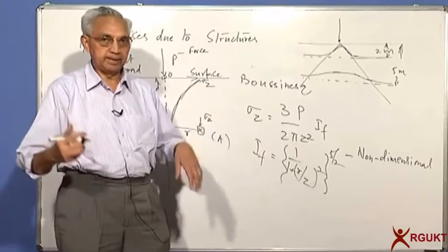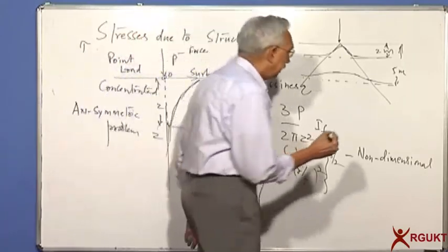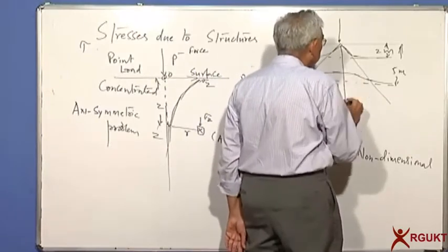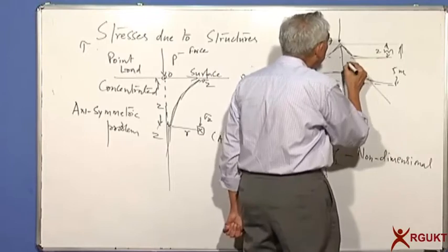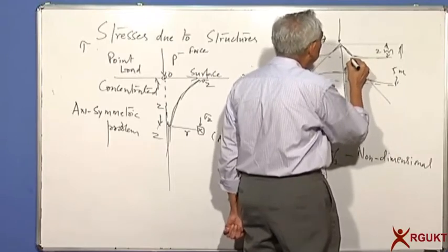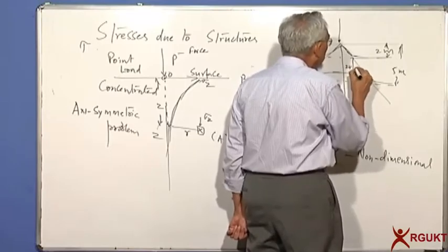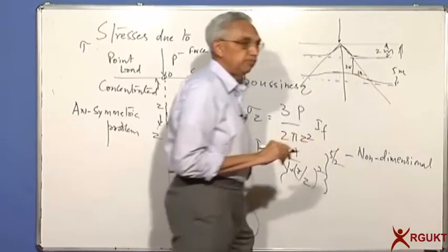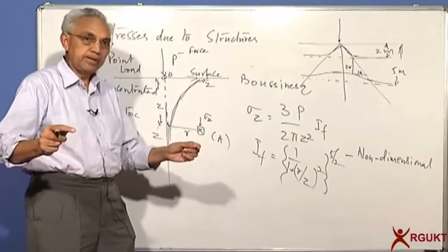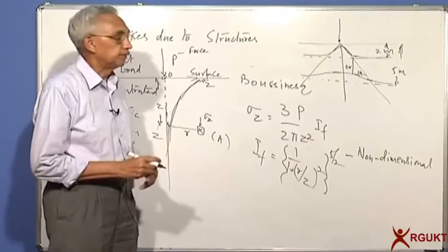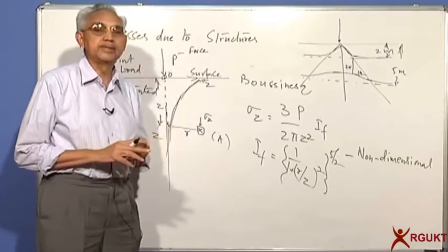So basically approximately it is decreasing with depth, and it's getting spread over a larger area. Before we got this analytical solution, people were taking it as 2:1 distribution. So if I go to a depth of 2, the variation would be 2 vertical and 1 horizontal. This is called 2:1 variation. So if you are going 2 meters, the load is spread 1 meter farther apart. So that's how we calculate the distribution. But we don't need to go for that simple one.